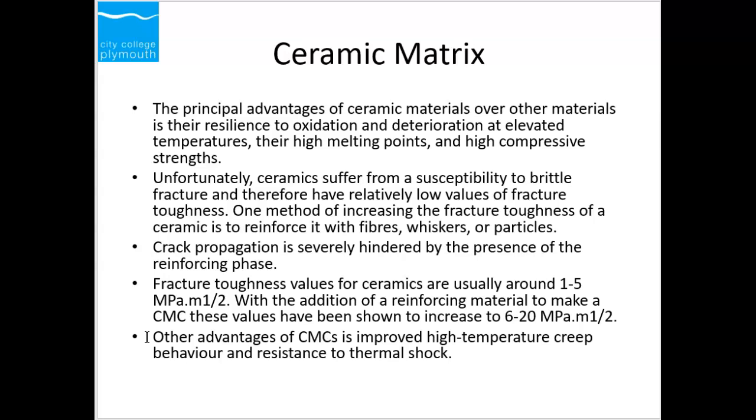So in summer, you will see the concrete expand, but the aluminium rods expand more than that, so they will protrude out. And in winter, the concrete will contract and the aluminium rods will go in. So they will lose the bonding within 12 months, once they have seen the whole season. And then there is no point, and they will cause more damage.